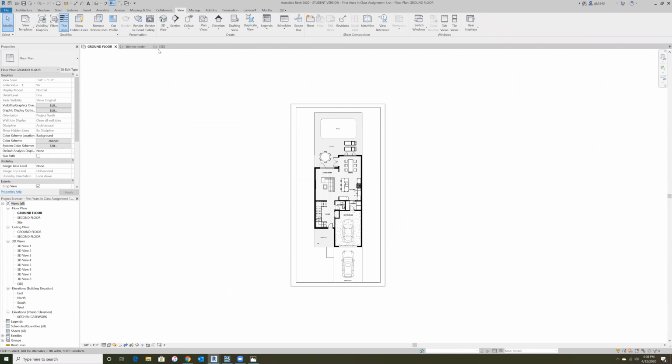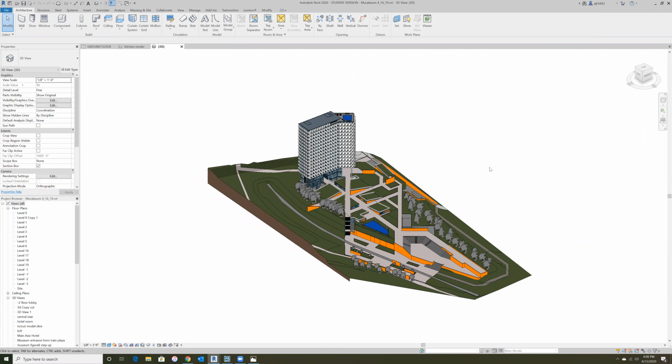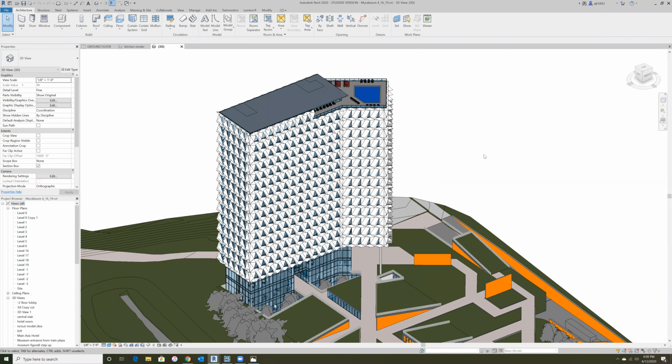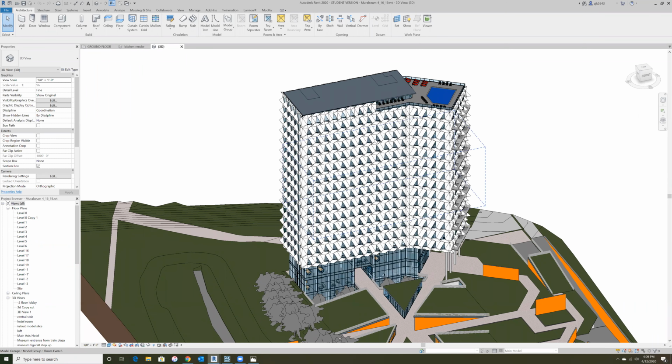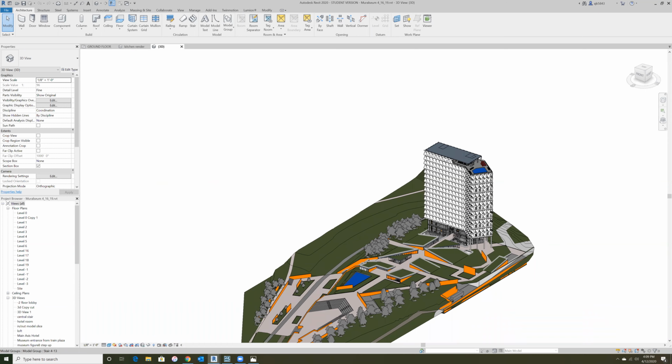So now Emily's going to show some of the workflow for importing a Rhino model component into a Revit file. So this was another fourth year project, and you will often get some criticism that Revit can be constraining, can start to limit your design. So this is where using Rhino and Revit combined can really take your project to the next level. So this is a facade panel applied to the upper portion of this hotel here. So it's a linked Rhino file that has been brought into the project, and each side is an individual project that is brought in from Rhino.